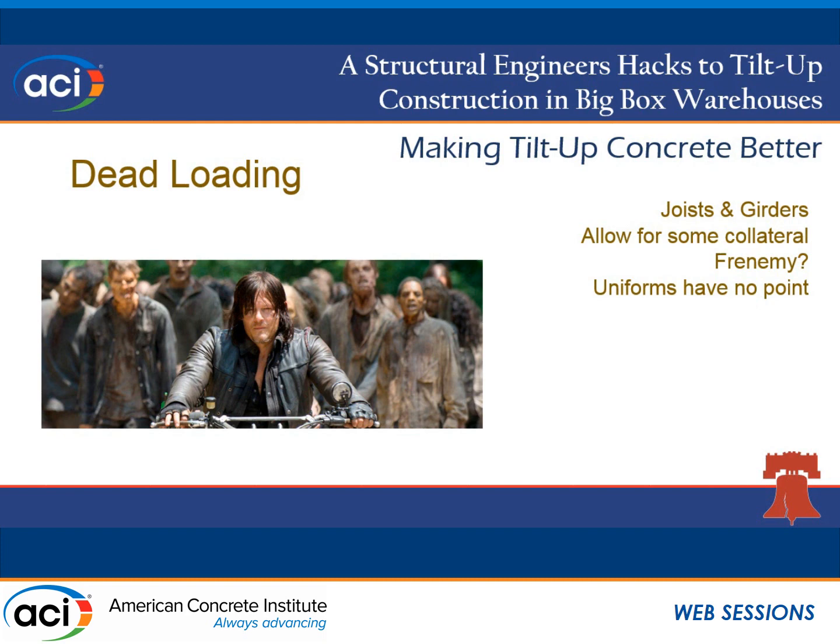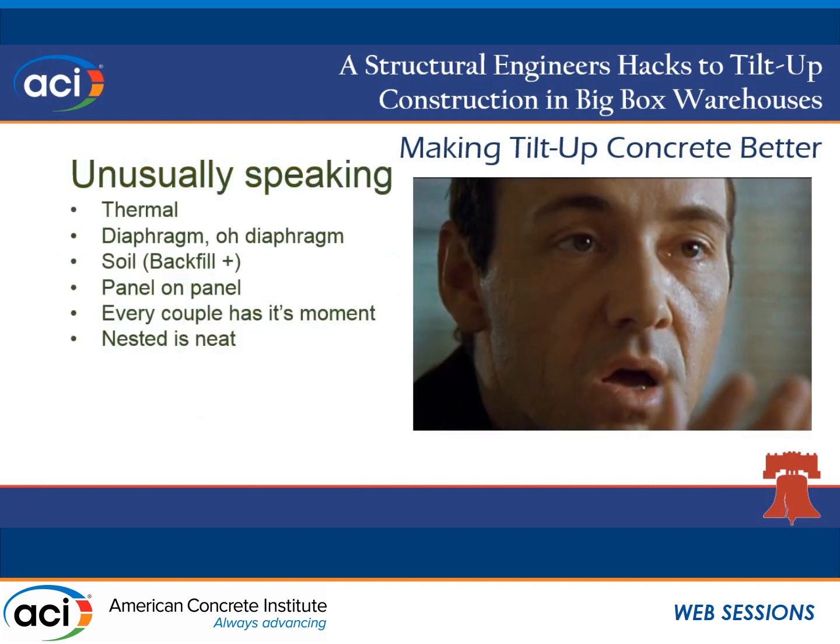The other thing to remember, and especially I'm looking at people who've done buildings that have process designs where someone says, oh, there's a 30 PSF collateral to account for conveyor loading. Understand that 30 PSF is actually going to be hung from every 3rd joist. So that 2-kip load has to be dealt with as a 2-kip load, because the joist girders, whatever, are going to have to deal with that individual loading, and it's a different animal, and doing it after the fact is a giant pain in the butt, which is something I was dealing with just before I came here.